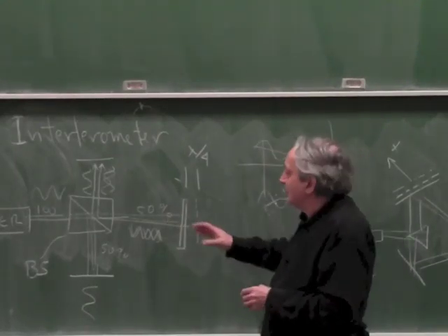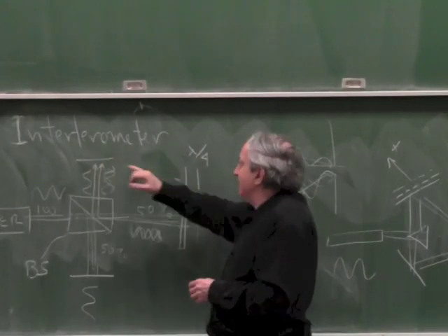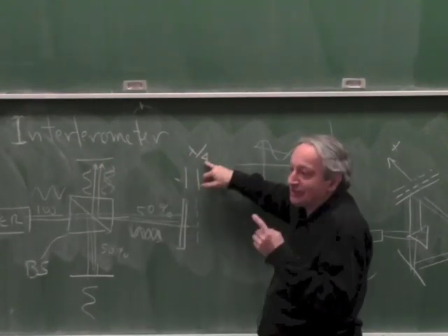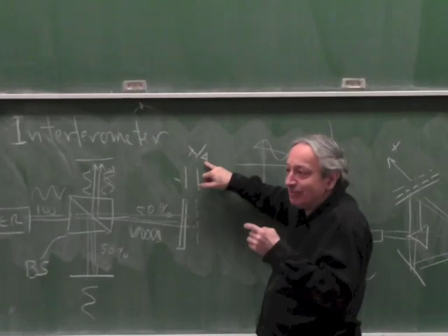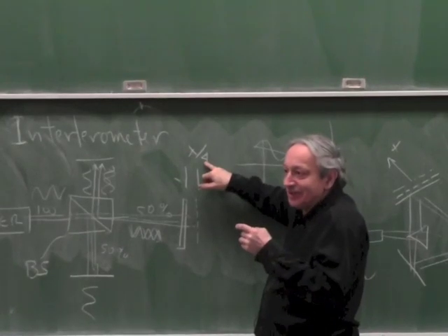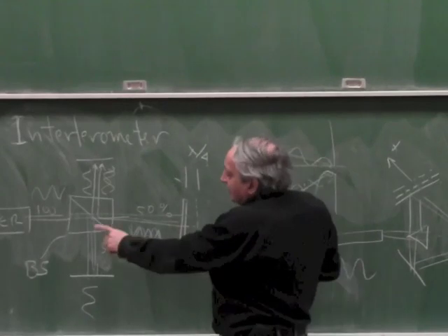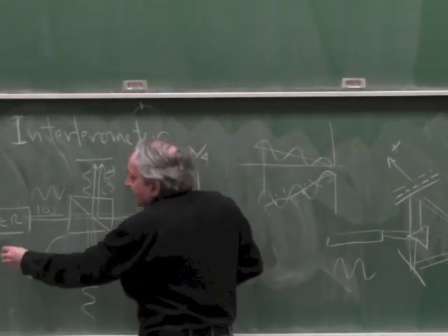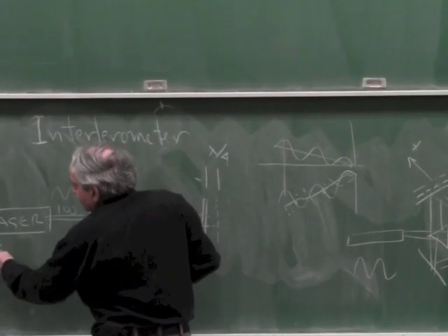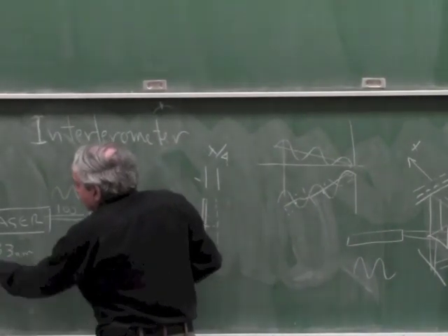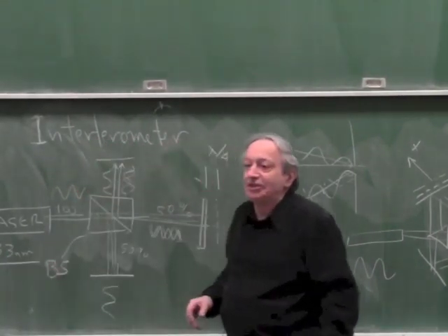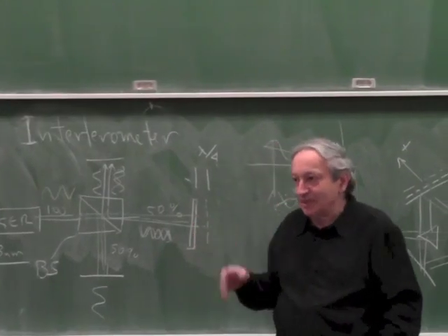because not only does it switch from dark to light with a quarter of a wavelength of light, you can interpolate between, right? Typically this is done today with red light. Today this is typically done with 633 nanometers, because that's the wavelength of the helium neon laser. You need a very stable laser.